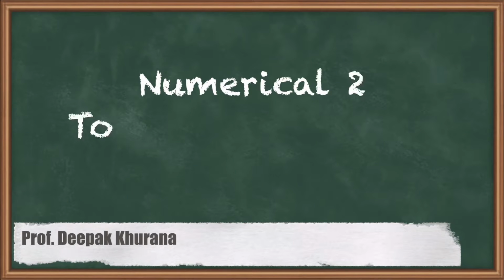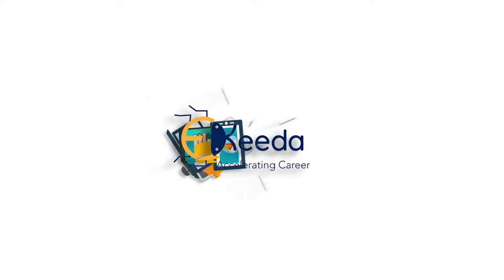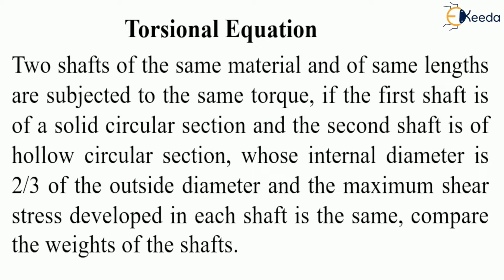Hello students, in this session let us solve this question of torsion. In this question it is given that two shafts of the same material and of same length are subjected to the same torque. If the first shaft is of a solid circular section and second shaft is of hollow circular section whose internal diameter is 2/3 of the outside diameter and the maximum shear stress developed in each shaft is same, compare the weights of the shafts.